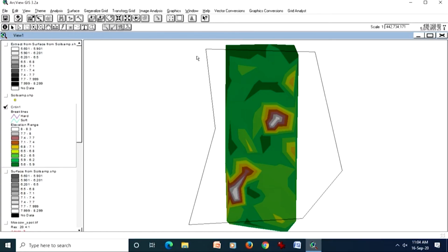So that is one of the limitations with the TIN. However, as I have said, if you are ultimately going to make a subset, better first make the subset of point data and then create TIN. There will not be any big problem in that way. But the boundary issues will always be there.